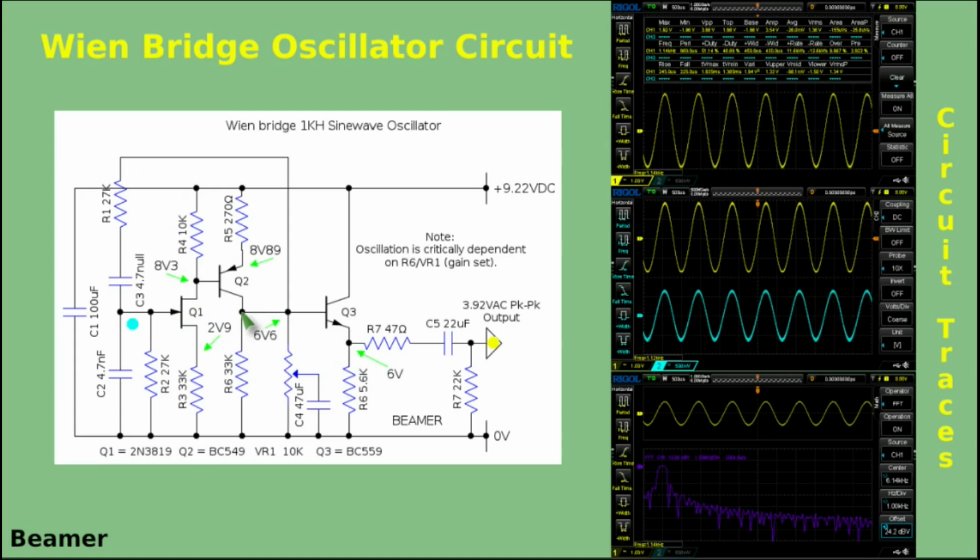So I'm describing something that is actually quite critical, and that is true. I've mentioned it up here. So we need, and I used a 10-turn potentiometer here. If you have the gain too low, the oscillator will be damped and it never reaches continuous oscillation. If you have the gain too high, you reach a point where the oscillation is distorted. Well, obviously somewhere in between the two is the point that you're after.